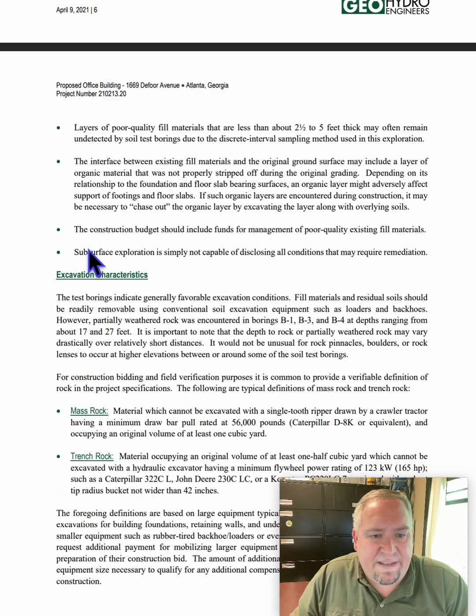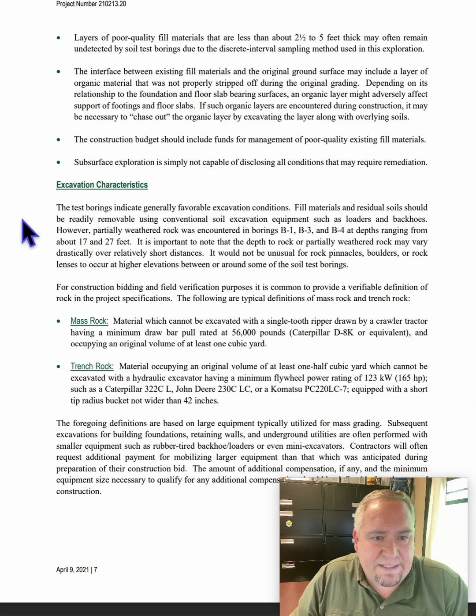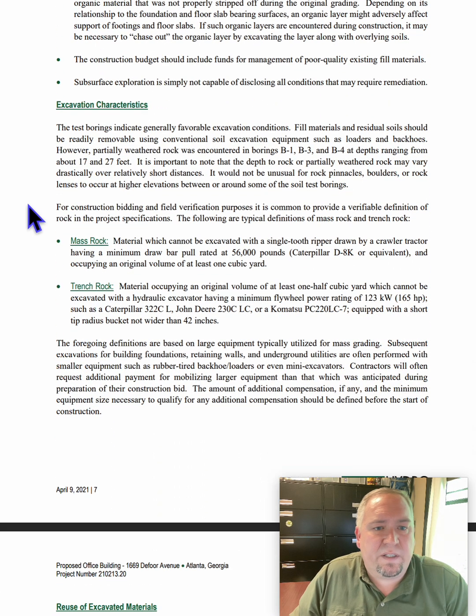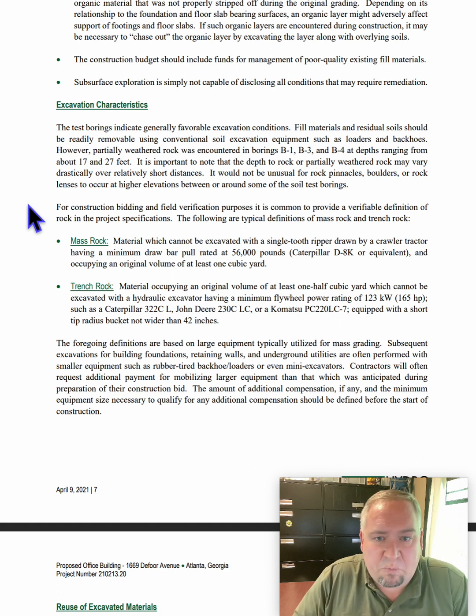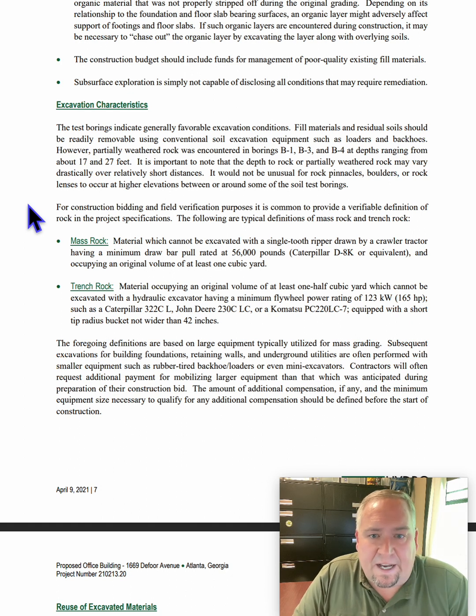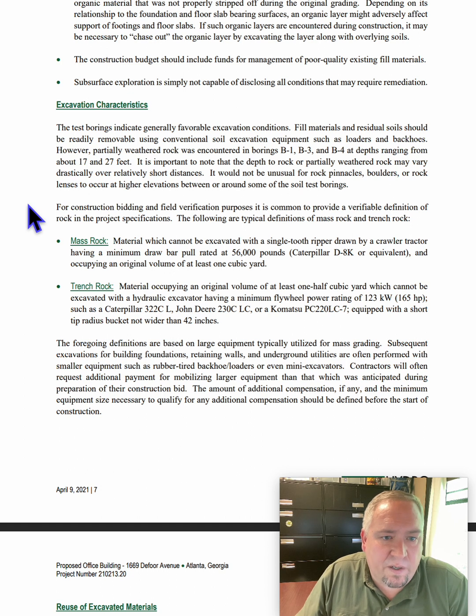Let's see, excavation characteristics. For this one, the test borings indicate generally favorable excavation conditions. So they're saying, hey guys, excavating contractor, it's pretty good, shouldn't be any problems. Fill materials and residual soils should be readily removable using conventional soil excavation equipment. That's what they kind of described earlier.